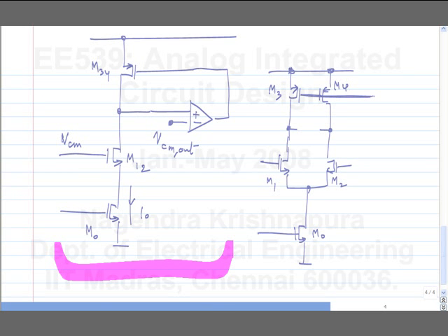Of course, if we do this, the common mode will be stabilized, but then we can't use the differential amplifier, right? For the differential operation, the circuit should still remain the same as before, but only for common mode, we need to have feedback around the upper current sources. Whatever we use for feedback should be sensitive only to the common mode voltage.